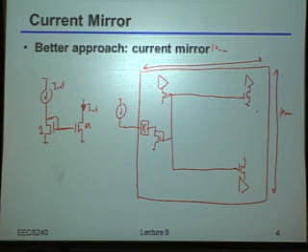Okay. So you said you're going to have voltage drops across the wire. Now, I want to be very specific about one thing. Which wire is going to have voltage drops? Yeah? Well, ideally, there's no current, so there's no voltage drop. So which wire has no current flowing through it? Like the big one. Okay, so this big red one, you said ideally should have no current flowing through it. And indeed, if there's no gate leakage in the transistors, there should be no current flowing through it.